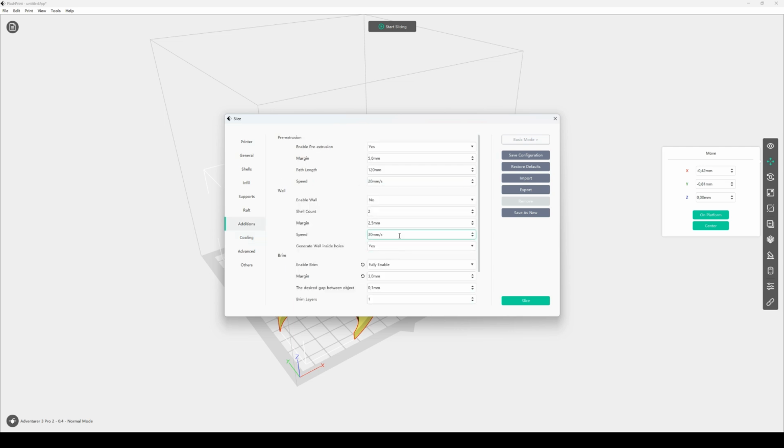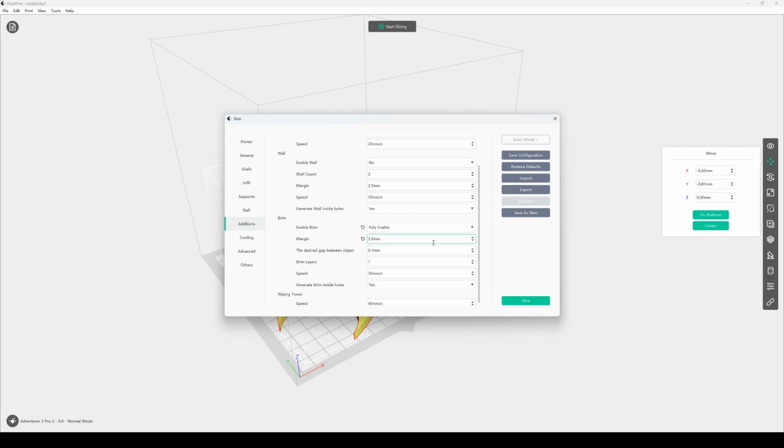Well, regarding the brim or raft, I also watched some video where they said that using a brim, let's say 3 mm for instance, but inside holes should be set to no if you're doing like screw hole type of holes, because for some reason that could lift your model off the platform or something like that.